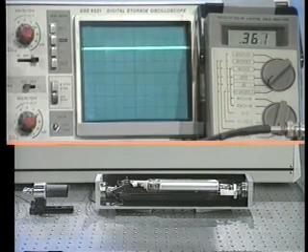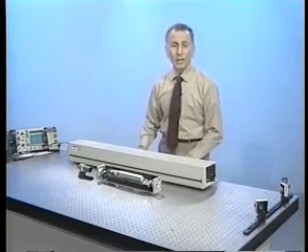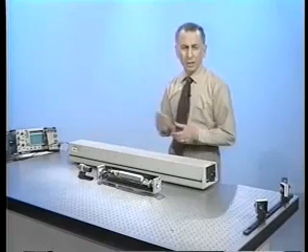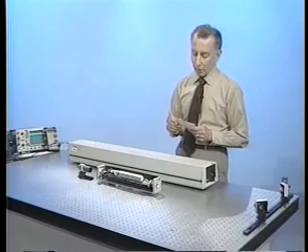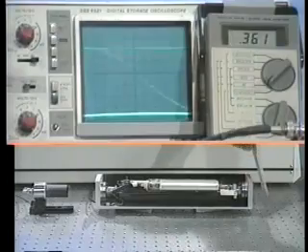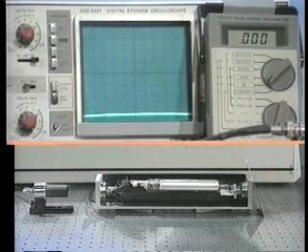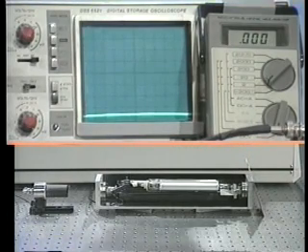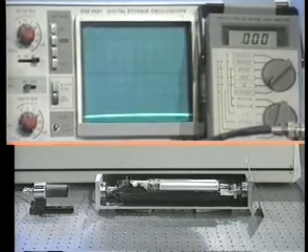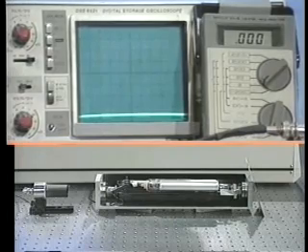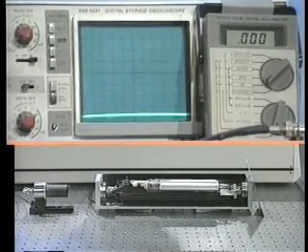Now you may wonder that maybe what we're getting, when I turn on the amplifier, is light from the amplifier that hits the detector. It's not really amplification. So to prove this, what I'm going to do is block the beam of light going into the amplifier so that there's no light going on the detector. We're back to our 0 on the meter. And now I'm going to turn on the amplifier just by itself, just to see if there's any light from the amplifier falling on the detector. So here we go. Watch the meter and the scope.